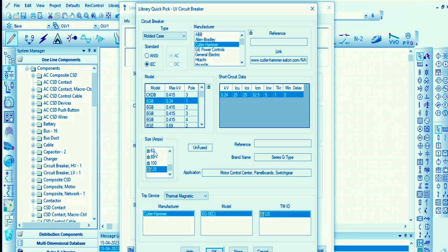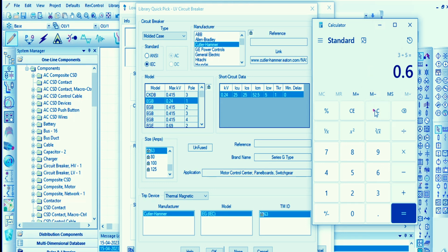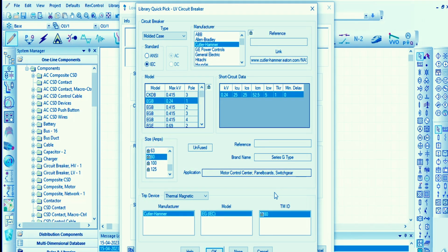And the size of the amperage we are going to make, for example, let's do a simple calculation. So we are having at least 20 kilowatts, or 20000 watts, divided by 240 volts. So we would like to go for at least 80 here.